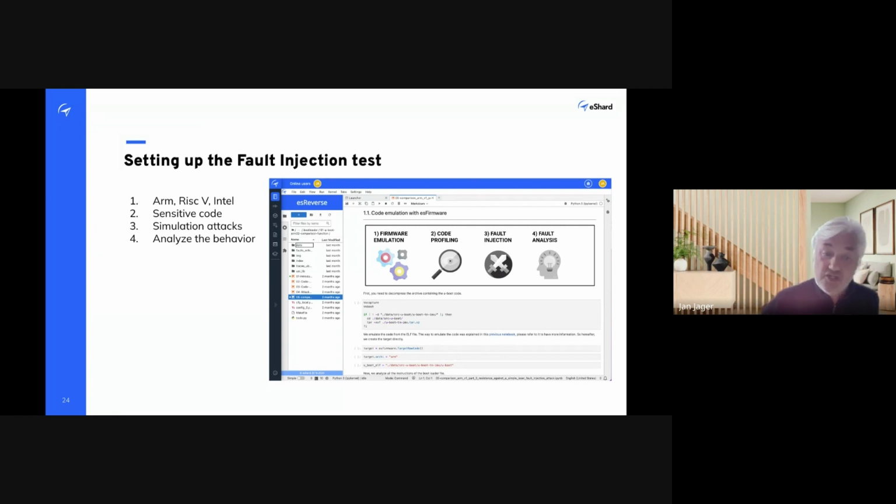Another thing that you need to think about is looking at the hardware. Do you also want to have an emulation of all the references to other hardware that it uses? Because it could be that there is a special AES check or a hardware check that you want to emulate, or maybe replace with a software implementation, or maybe you want to stub some addresses that are accessed in the firmware, but that you do not have available in the emulation. So those are considerations you need to think about. Do I want to stub, or am I going to implement the hardware references that are done outside the emulation architecture?